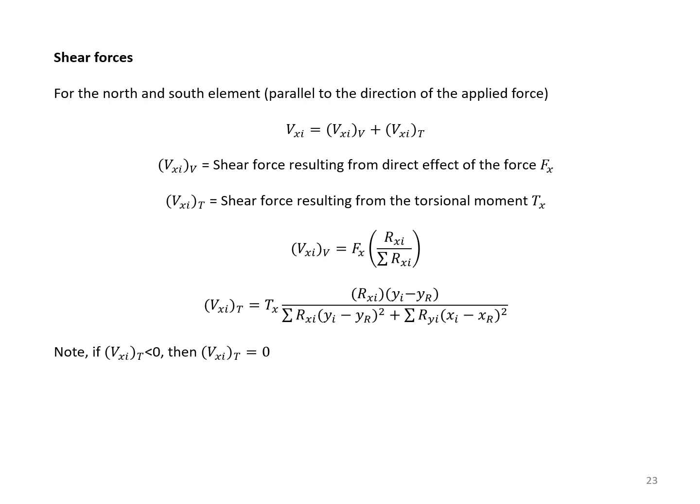All right, these are the equations again for the total shear, one from the direct shear, the other one from the torsional effect, and the equations we talked about before are here. And don't forget, if this term is negative, we use 0.